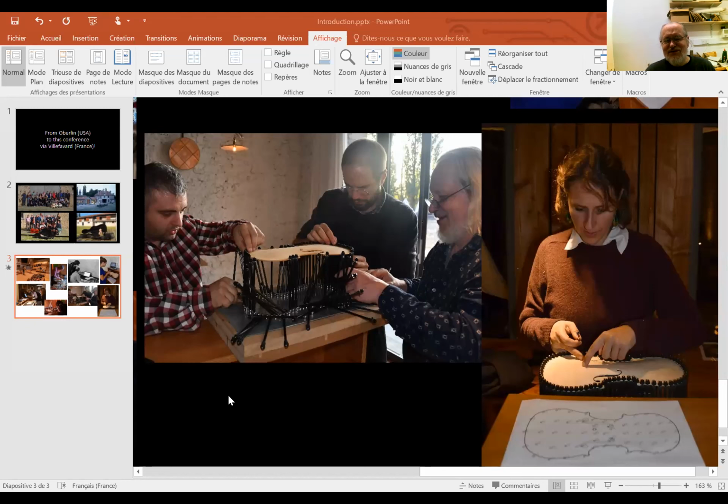But anyway, it wasn't the topic of this talk, but I think it is relevant to say that when you decide to do modal analysis, the boundary conditions are important. So if, for example, you want to know what a building might do in an earthquake, well, you make a scale model, and you put it on a table that maybe shakes horizontally.